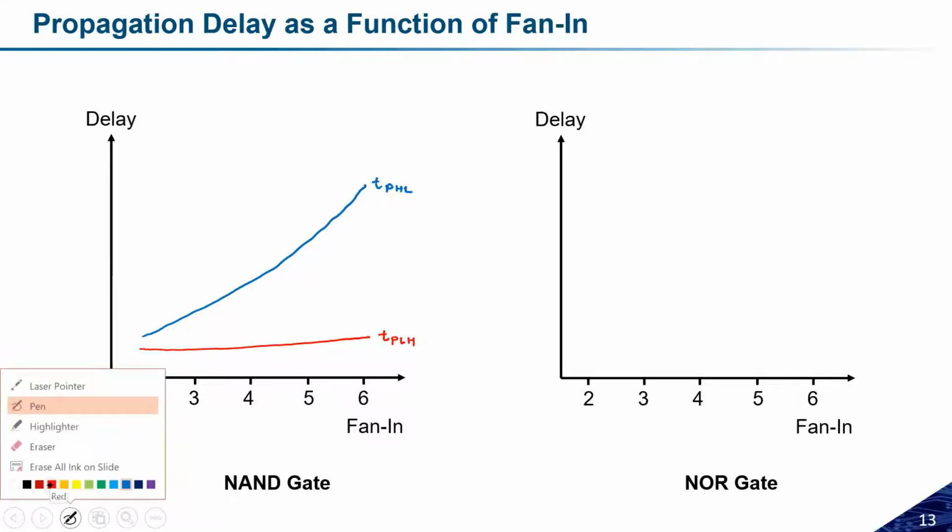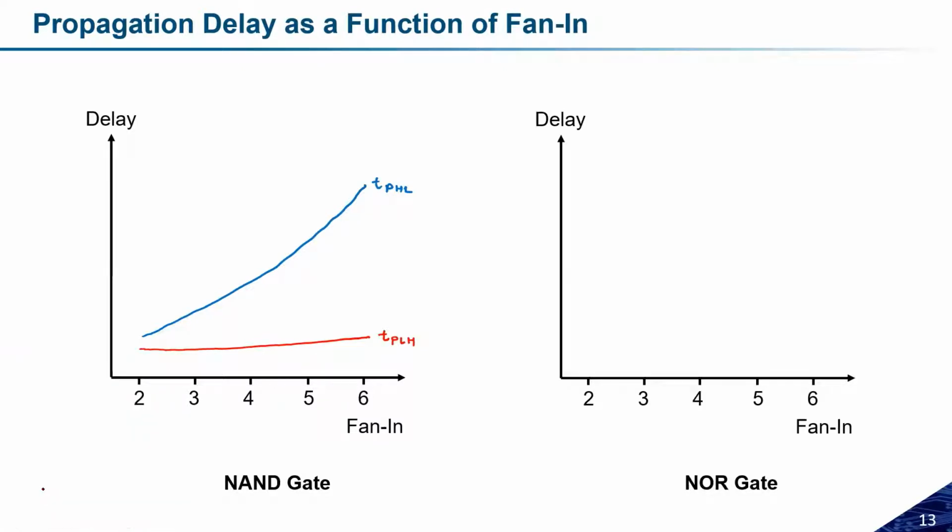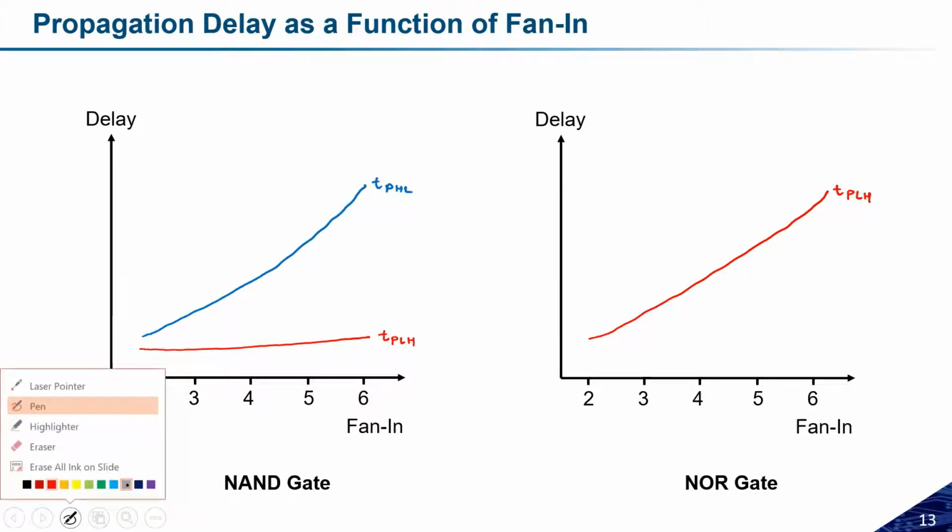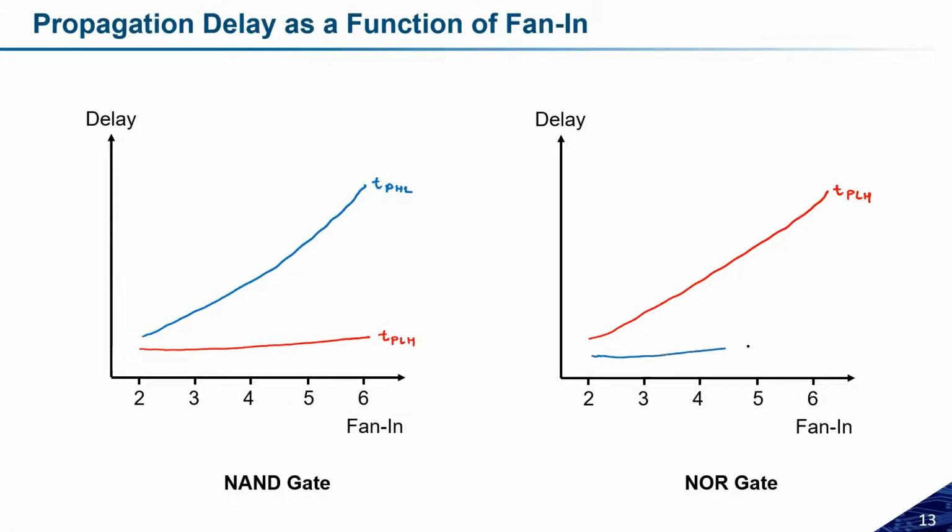So we just understand how it will be. Let me change the color so that it will be better. So this is the TPLH, and this is how TPHL will look like. So these are the characteristics of both the delay components as a function of the fan-in.